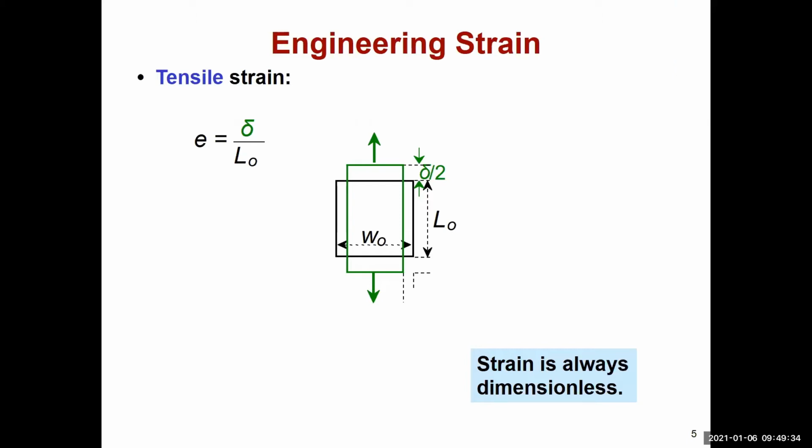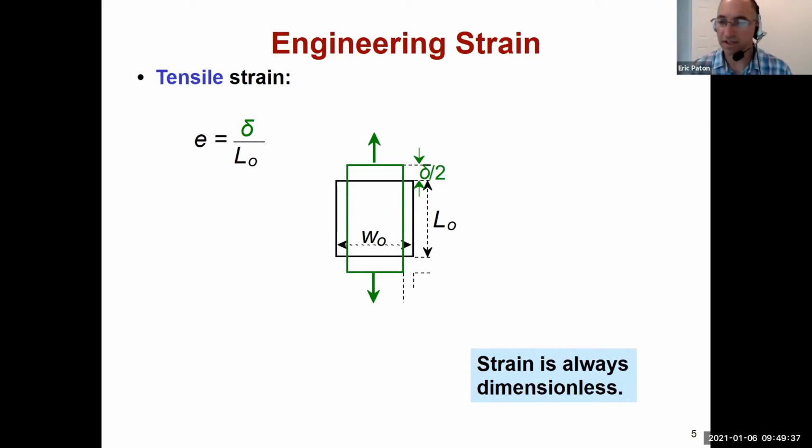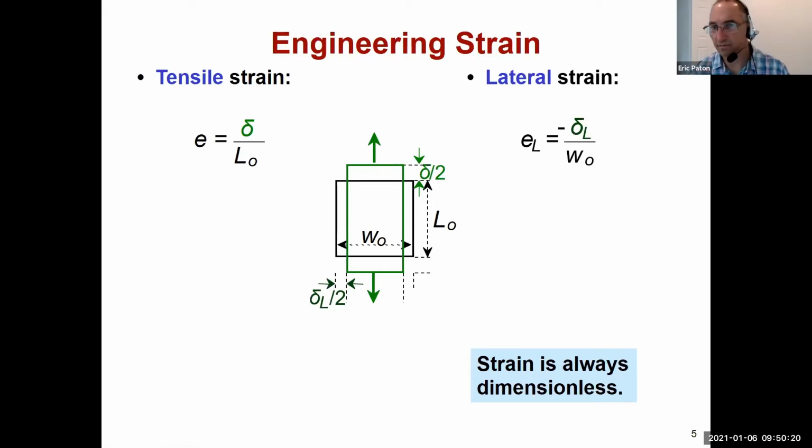Poisson's ratio. Exactly. Good job. It's the Poisson's ratio. So that's another thing that you're going to be able to calculate from the data that's going to be provided. And that's the reason why we put strain gauges on our tensile specimens in both the transverse direction and also in the parallel direction. Okay, so by just looking at the differences in those strain gauge readings, we can calculate Poisson's ratio. All right, and there's your lateral strain.